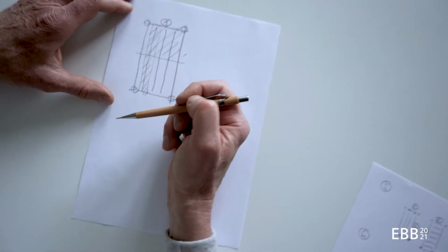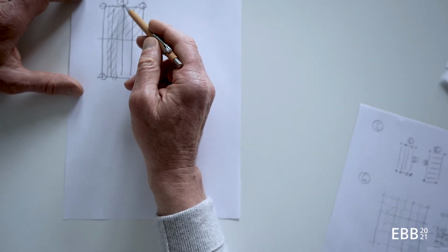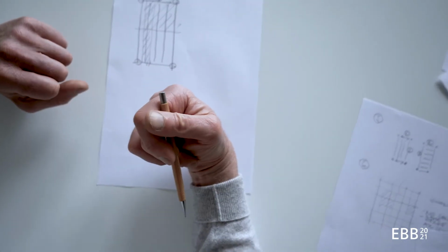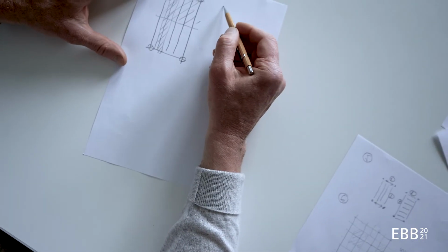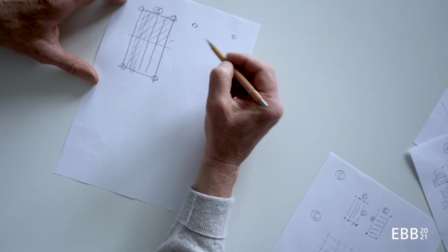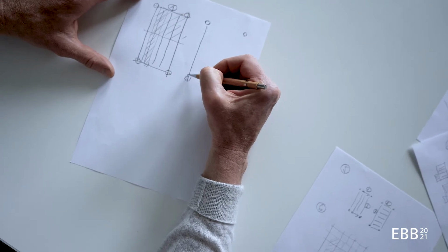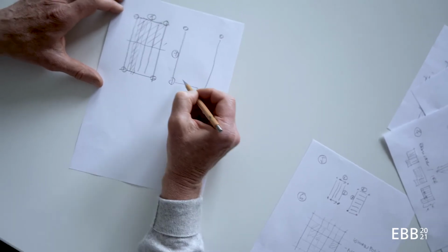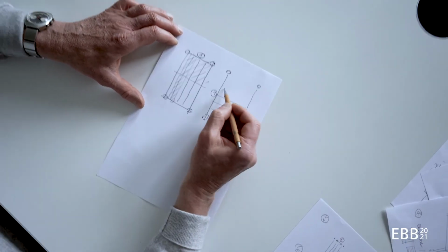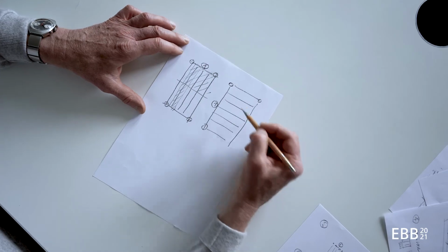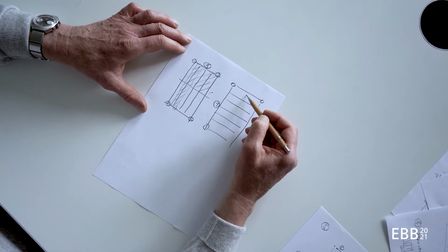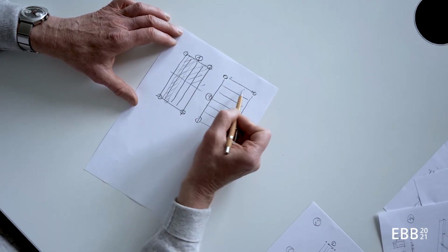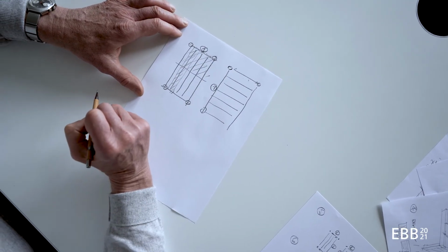So the smaller span will make that the primary beam and the secondary beam will be more alike in their dimension. So if I switch this around and I say, well, this is the primary beam and the secondary beam is in the other direction, then you will see that the span here of the secondary beam now corresponds to the primary beam in the first example.